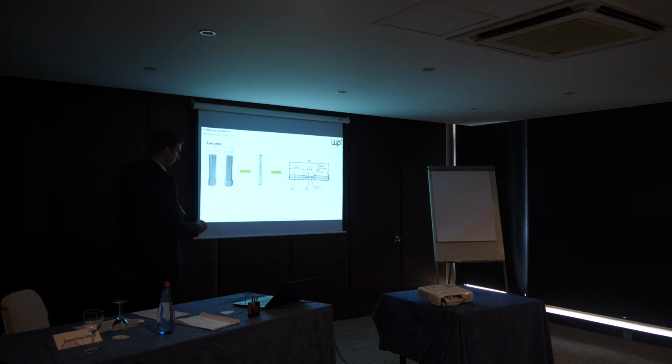It is about 10 millimeters. Because the accuracy of the potential drop method increases with a smaller distance of the probe. So perhaps you can enhance it if you get closer. The measured voltage gets smaller, but the resolution gets higher. Okay. So perhaps you can really enhance, that's a really good thing. Thank you. Thanks.